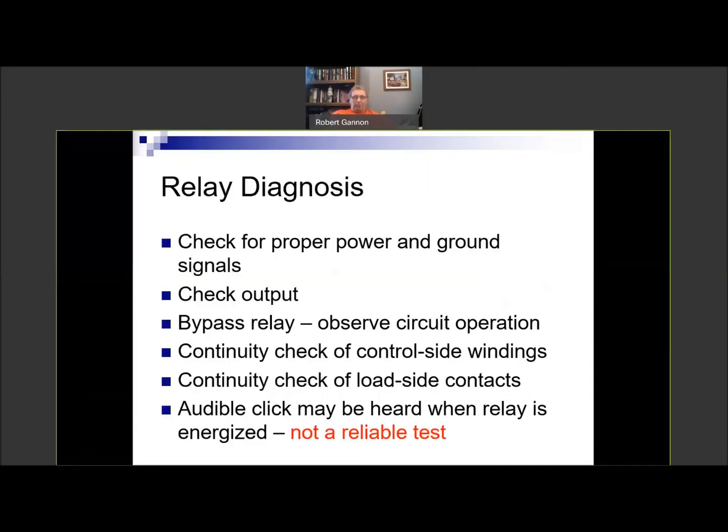So I do have one, I put it in red down here. You might hear an audible click when a relay is energized. It is not a reliable test. So going back to my example of that Honda AC clutch relay, it sounded like it worked, but no AC clutch until that relay was replaced.